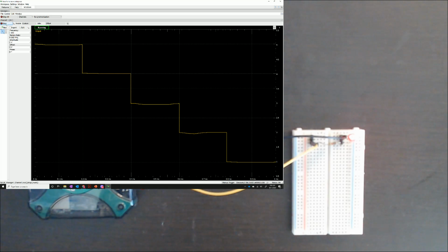This is, as we discussed in an earlier video, because our eye and my webcam only see the average brightness when the brightness changes at very high frequency. If we stop this waveform and change our frequency to 1 Hertz, we can then run again, and first we can observe that our time axis in our sample waveform is a total period of 1 second. In other words, the level actually changes every 0.2 seconds. As we run this on our actual LED, we can see the LED changing brightness levels.